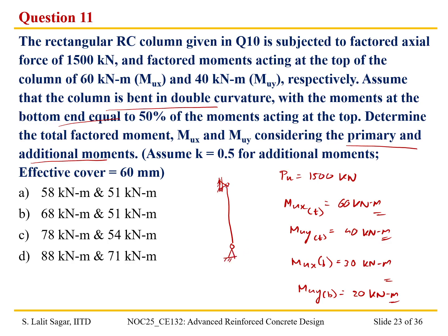Let us assume that it undergoes this deflection profile where there is sagging at this point, M1 subjected to P, and it is subjected to this hogging moment at the other end, that is M2 and load P. Because it has this curvature at this point and the opposite curvature, and there is a point of inflection in between, this is called the double curvature.